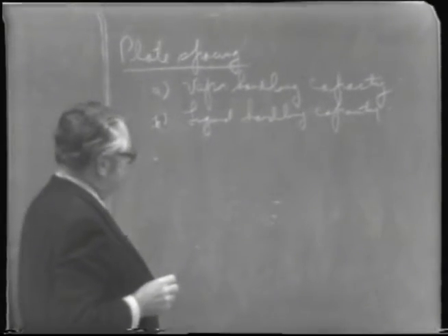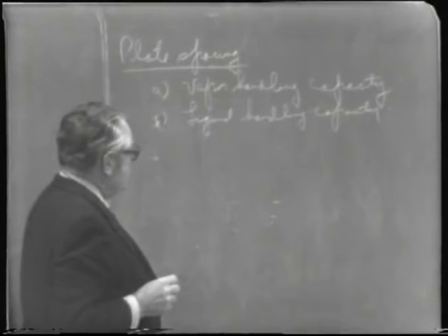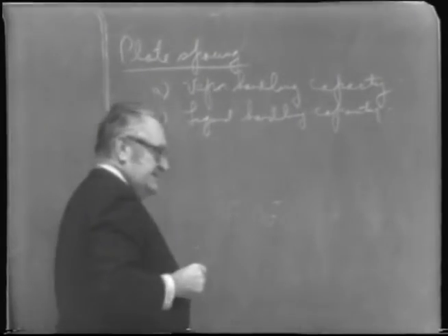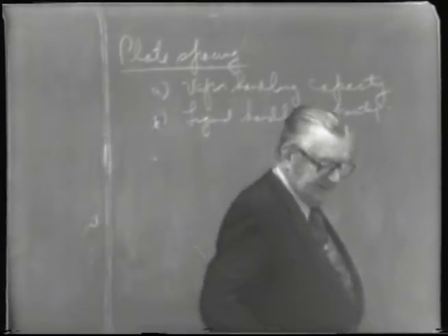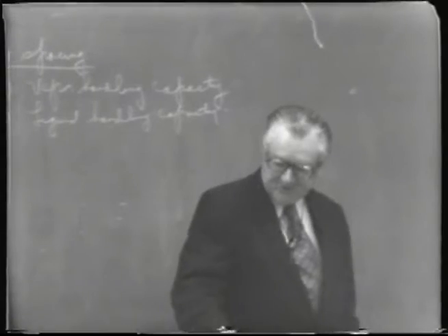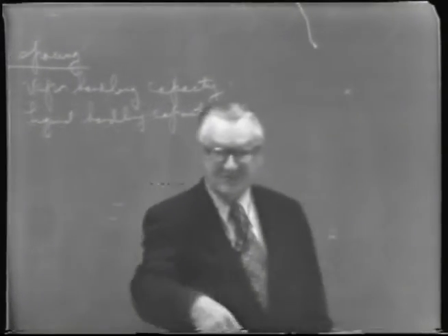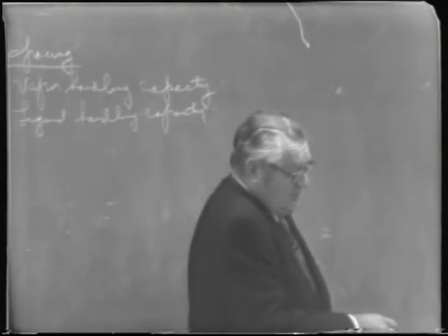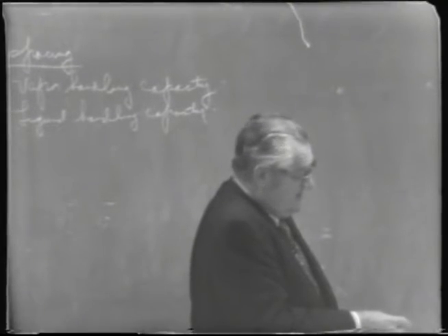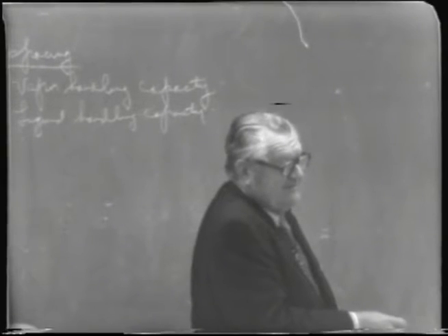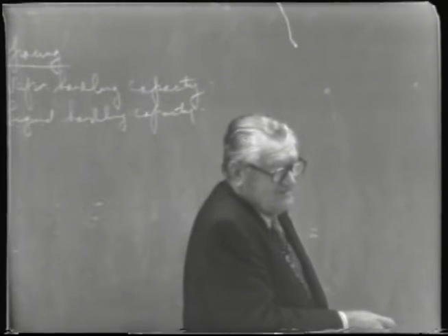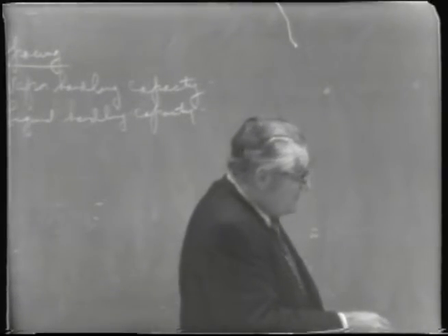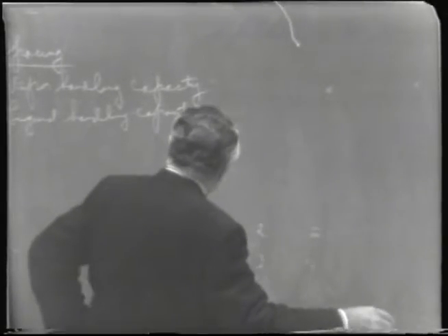Now, as far as the vapor handling capacity is concerned, I'm not going to take time to go into the mathematical treatment of this, although there is in the textbooks considerable mathematical treatment of how you arrive at a proper plate spacing. But in reality, it's quite empirical treatment. It's still subject to some controversy as to how accurate the data is.